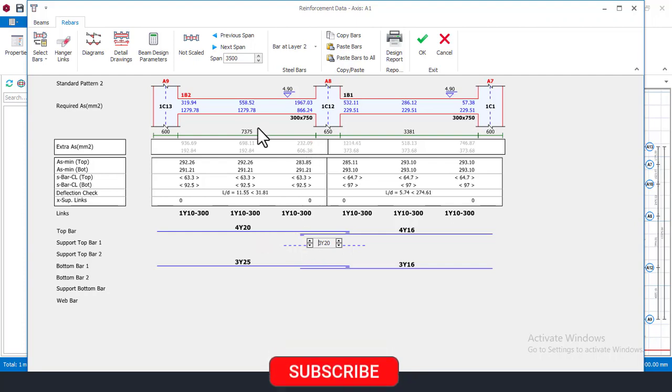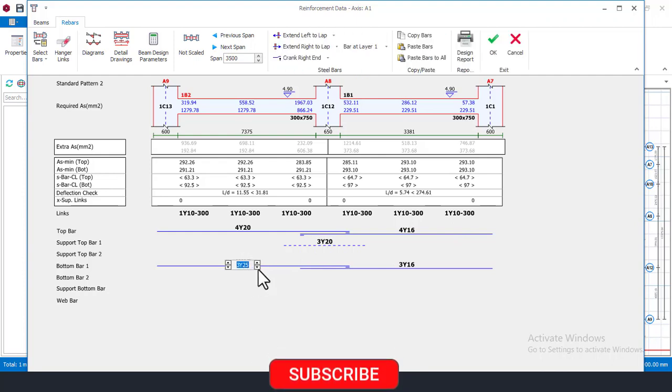So right now we have, at this 7.37 meters beam, 4Y20 first, and at the support here we have 3Y20 at the top. And on this span that has 3.381 meters, we have 4Y16. As you can see that. So also at this bottom now, I'll have to decrease this and then increase the number to 4.